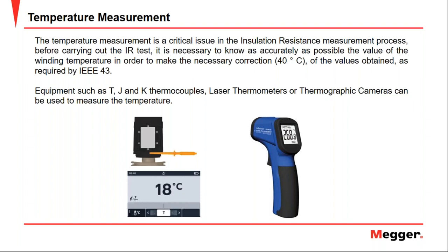We can use several pieces of equipment for this purpose. We can use T, J, or K thermocouples, laser thermometers, or a thermographic camera, whatever you want. But we have to measure the temperature. It is a very critical variable of the system.